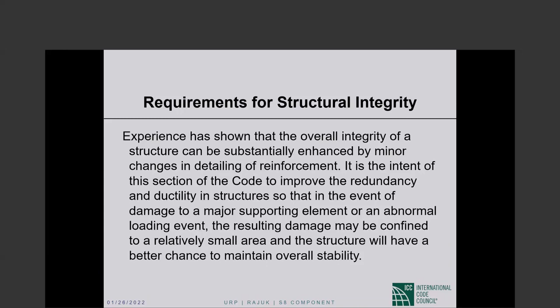So I will start with the question on torsion first. Okay. So for a four-leg stirrup, say four 12 legs, can we assume the outer leg to transfer the torsion and inner two legs to transfer only shear? No, not only shear. All four legs will carry shear. Outer legs torsion and all four legs shear. Yeah.